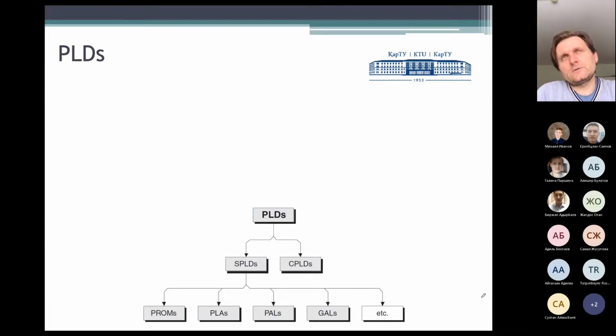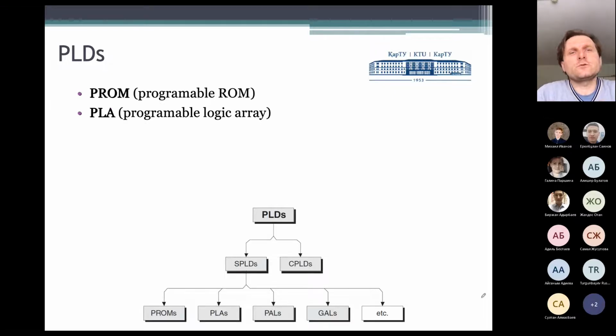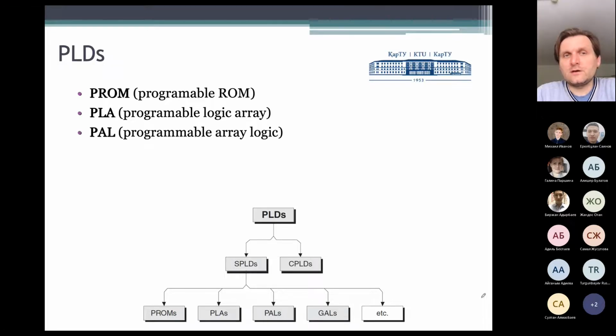They wanted to go another way, another path, to solve that digital technology problem. They tried to do something new. The new simple structure was the programmable logic array, and programmable array logic. Why are there two names? Because two vendors invented something similar. Programmable logic array is the natural name of an array with programmable logic elements, but another vendor had to change the name, because PLA was a trademark of one of the vendors.